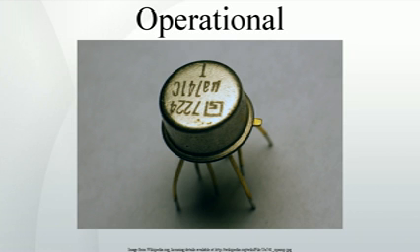Input offset voltage. The offset null pins may be used to place external resistors, typically in the form of the two ends of a potentiometer, with the slider connected to V+ and parallel with the emitter resistors of Q5 and Q6, to adjust the balance of the Q5/Q6 current mirror. The potentiometer is adjusted such that the output is null, mid-range, when the inputs are shorted together.